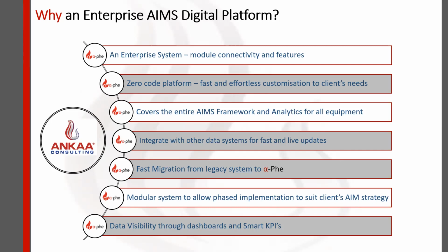And all operators desire and opt to extend life. We've done a number of life extension work. We find that if the asset integrity process is poor, then it's extremely hard to actually conclude how much remaining life you've got in different components of the asset. So an enterprise digital system will allow you to achieve all of those goals: integrity goals, management of major accident hazards, as well as achieving a life extension at end of asset life.